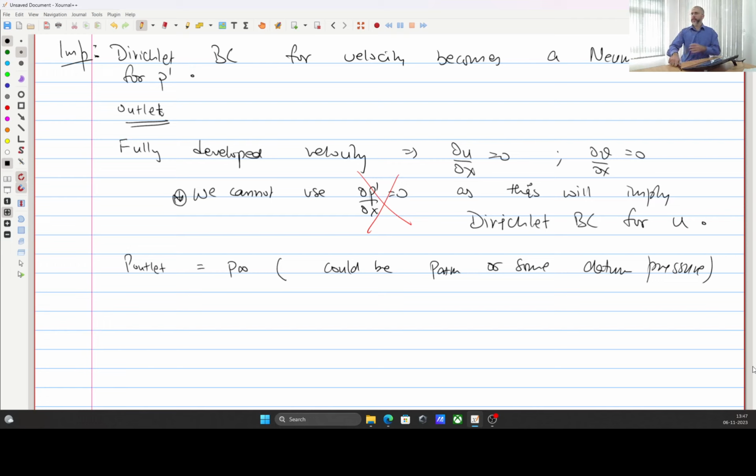So if you think of a pipe. Now, most of you mechanical engineers, if you see a pipe, if you have let's say very high pressure and the same pressure at inlet and outlet, will there be any flow? No, because there is no pressure difference. If pressure gradient is the only reason to drive the flow, there will be no flow. So flow happens because of differences in pressure.